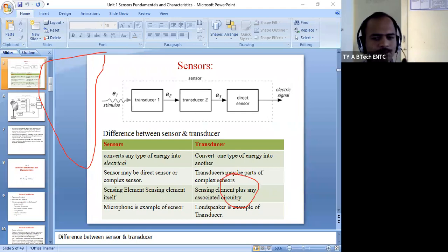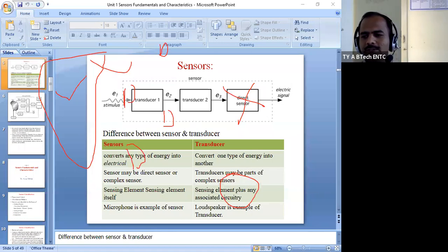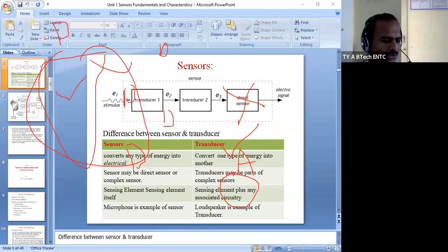So out of these 5, if a particular sensor 1 gives output in digital format, no need to go for A to D converters. 2 is having the same, digital only. 3 is having the same, digital only. 4 is having the same output format, digital only. And if the 5th one gives output in terms of analog quantity. So out of 5, 4 are showing output in terms of digital quantity, and only 1 generates output in terms of analog quantity. So how can we go for this?